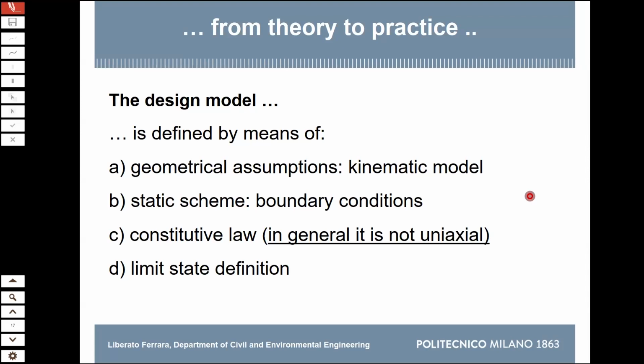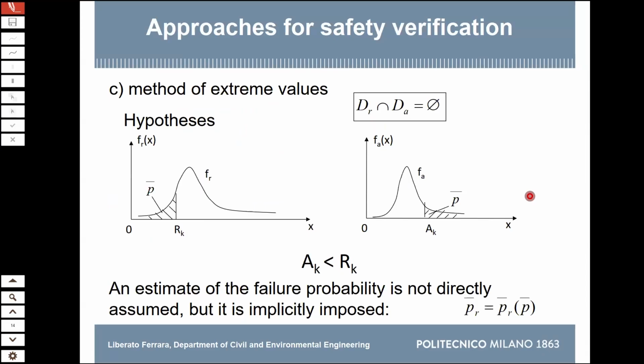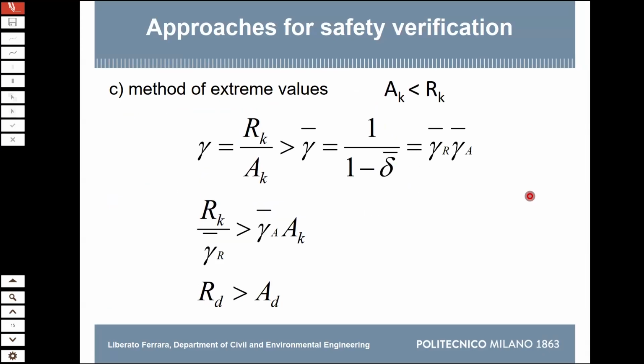You see, in geotechnical engineering, in this equation here, they put in another coefficient, which is the uncertainty of the model, because soil is a much more uncertain material than concrete or steel can be. We accept our models to be absolutely certain, deterministically certain. So the coefficient of uncertainty of the model is 1. But in geotechnical engineering, there is a coefficient which is the uncertainty of the model as well.